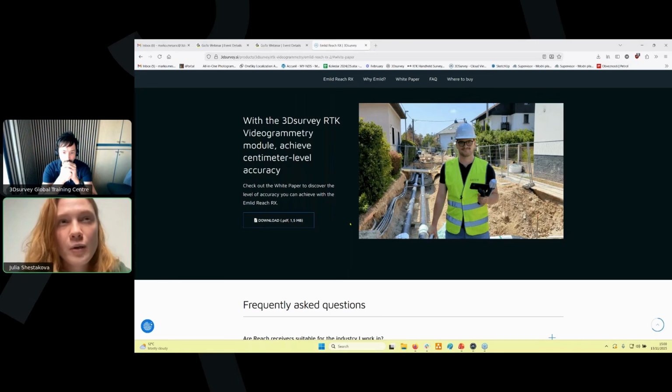It's just a question of the setup itself. The fact with the Reach RX and Reach RX2 is that they're small and lightweight, you can place them on this handle and easily work with them. Plus, the configuration process is super minimized. You configure just the correction input, position streaming is already enabled. So it's the easiest, the smoothest way to make it work.